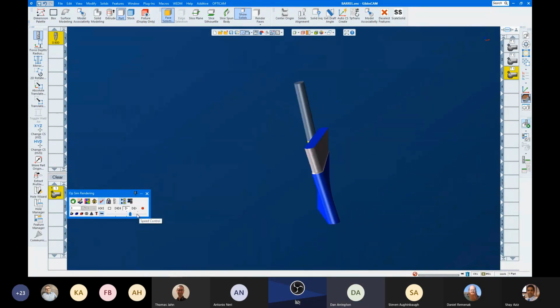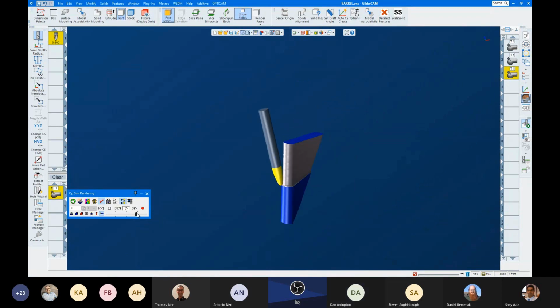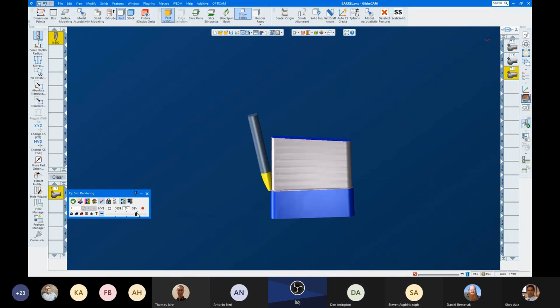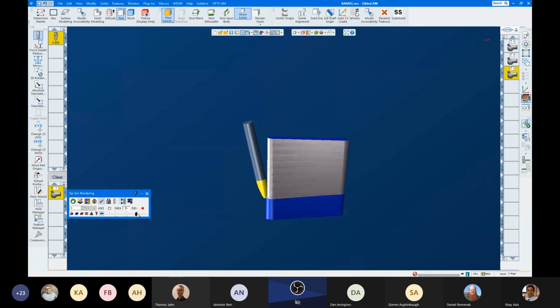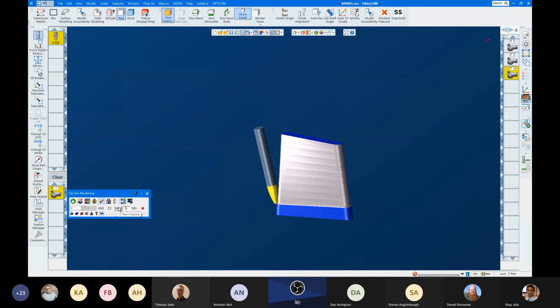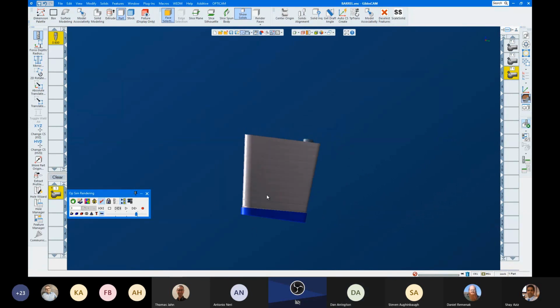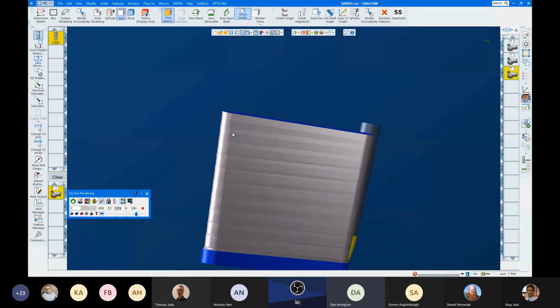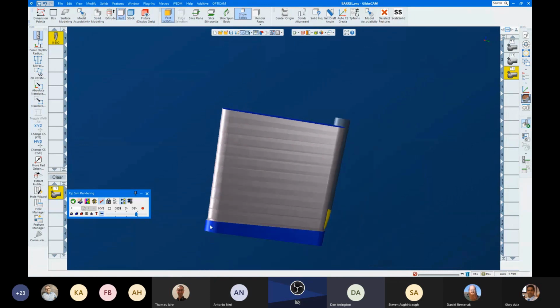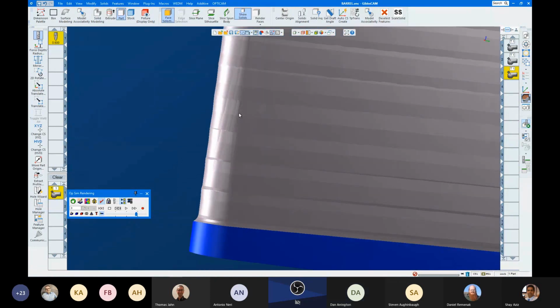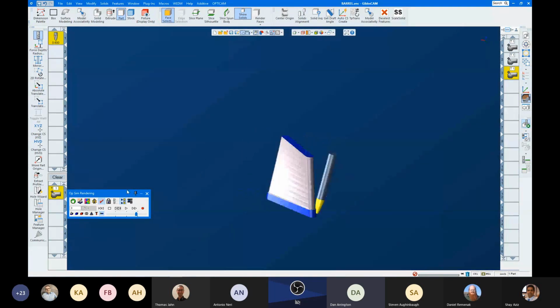And you'll see this. That's far enough that you can see the difference. Kind of smooth up here as we work our way down. The tilt changes, so the scallop height changes.